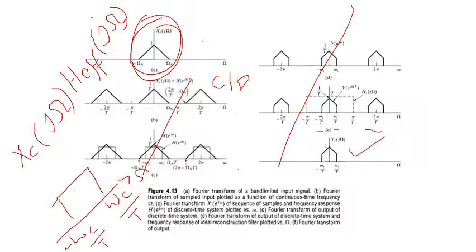So you can go back and you can check how we can apply. So directly applying H effective filter, we know that H effective filter is low pass here. So just applying this on the first copy, we can directly get this. So this is the purpose, that we do not need to do all these steps as long as we know that the input signal is band limited and this Nyquist criteria is satisfied. So you can read the caption and hopefully you got this. Let's move on to next slide.